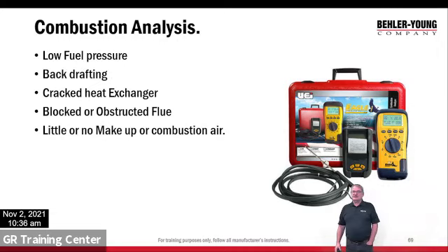So combustion analysis, this is another thing that's come a long way. This thing over my head is a combustion analysis kit. Nowadays, we can test the combustion. We can see how the furnace is running. What is our efficiency rating? What is our excess oxygen amount? Do we have CO? What's our CO level? Mostly we're going to have a little CO, but it shouldn't be much, and it's going to be measurable.